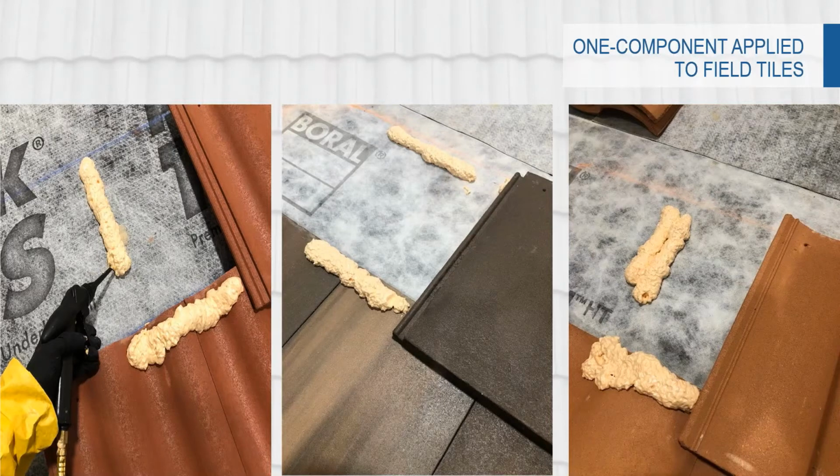This is a picture of the single component being applied to various profiles of tile. On the left, that's the medium profile tile. You can see the beads of adhesive going on the overlap of the tile, 3 inches where the tiles overlap, and then 1 bead of adhesive going directly on that underlayment. On that middle picture, that is a flat, low profile tile, 2 beads of adhesive as well. And on the right picture, that's the high barrel tile, and you can see that does require a little bit more adhesive underneath those tiles.